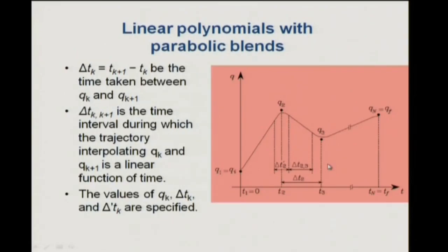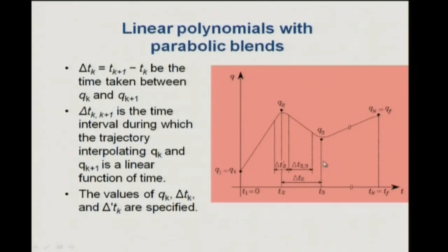Okay, now some people say even this is too complicated. Was it complicated? No, nothing is complicated for this class, right? So, if you look at it carefully, what is my issue? The issue is that I want smooth transitions, I do not want jerks. So, the proposal is very simple. If I have to go from Q2 to Q3, I can always draw a straight line, and then going from the next point to the next I can draw another straight line. Only problem is that at the junction I will have discontinuity of both velocity and acceleration.